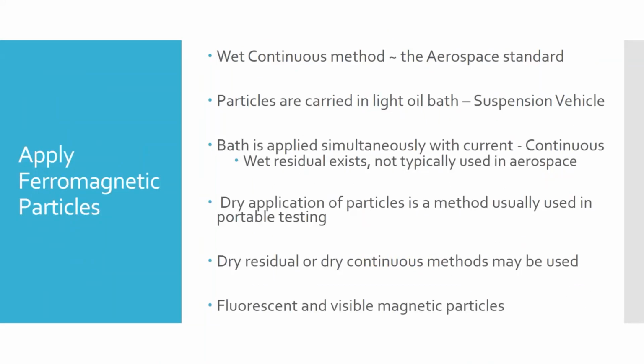And this is the aerospace standard, unless you're doing on wing. But most of your NDT, most of your magnetic particle inspection is done off wing. It's parts that can be removed, they're inspected, and then they're going to be reinstalled at a later time.